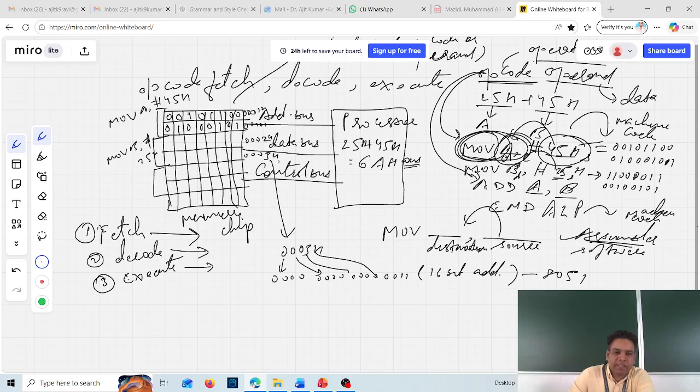So for each location, 16-bit addresses are assigned. Now, there is a register inside the processor called the PC, the program counter register, which will store the starting address, and not only the starting address, but all the addresses from where the instruction has to be fetched. So the starting address is 0000H. This address from the PC will be loaded on the address bus. This address bus, being 16 bits, is 16 electrical wires, which will carry individual bits, and this address will be received by the memory chip. Now there is an address decoder circuit which is not displayed here.